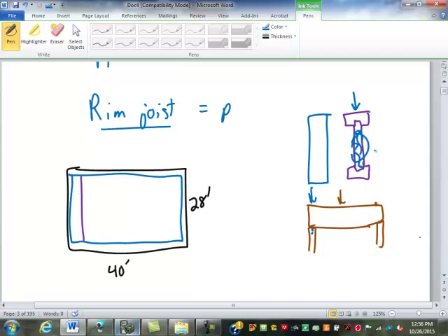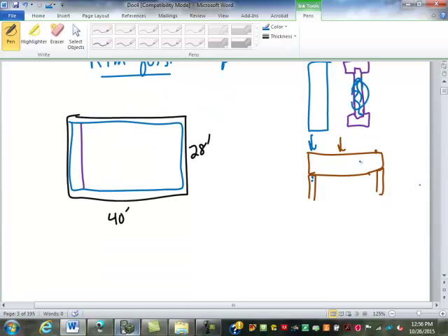Yeah. So I mean, 14-foot spans usually only like a 13-foot 2 span, really. You still get away with 2x12s. 2x12s would take you up to like 16 feet. If you got over like 16 feet, then you'd have to bump it up to something bigger than 2x12 even. Yeah. 2x12s themselves are heavy enough.